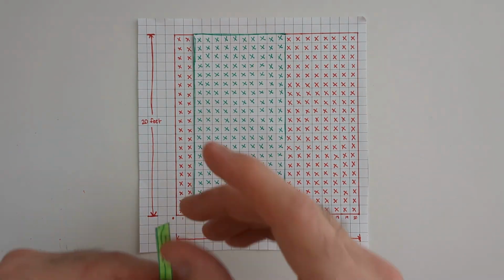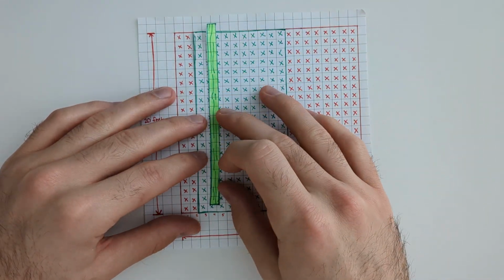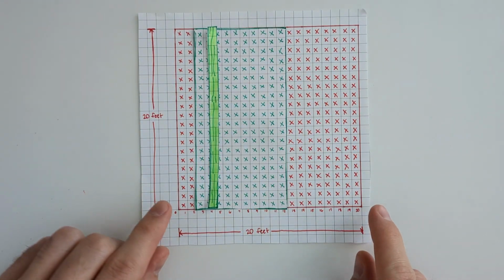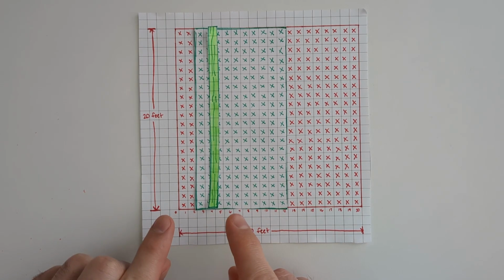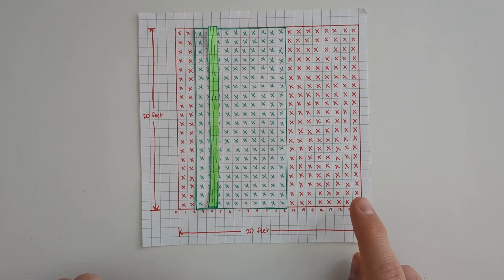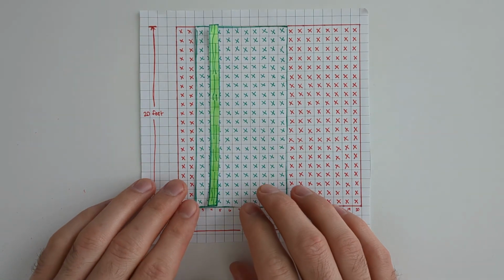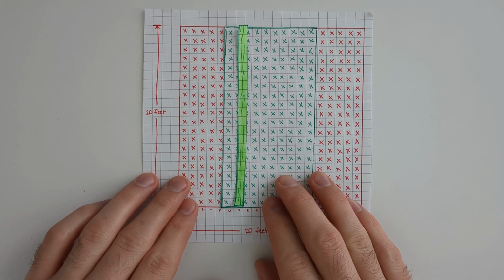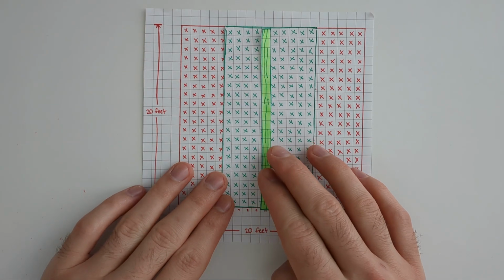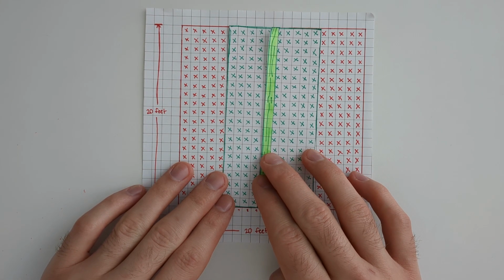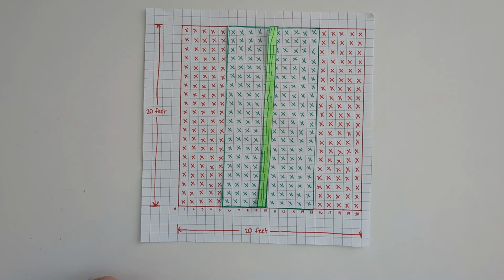The only thing that will change is the contribution of the walls on the sides. You can see here, since we shifted our tributary area that way, the contribution of this wall has gotten greater, while this one has gotten less. Now, we want to make it even. We want to make it fair to the walls, so we'll keep our tributary area in the center, which means we'll install our beam in the center.